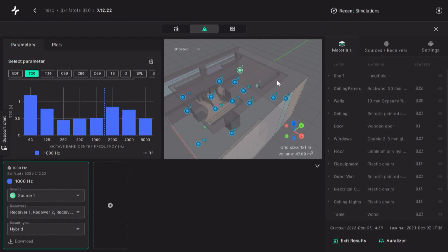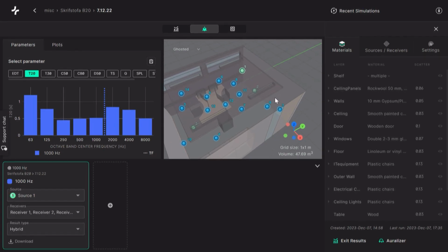And the center of the ceiling, where we have concrete, is also around 9 square meters. So by switching around and placing the absorption in the middle and defining the perimeter as being made out of concrete, we are actually not changing the absorption area in the room itself. We are only changing the location.